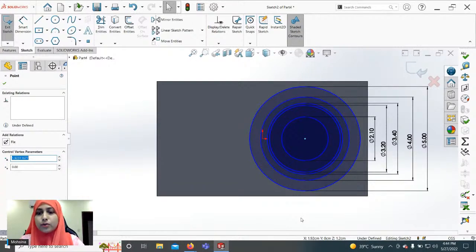It is important to have the part defined because if the part remains underdefined and we go on to connect parts together and create an assembly, modifying the sketches, changing the dimensions after creating the parts will affect the complete part and can also make the assembly explode.